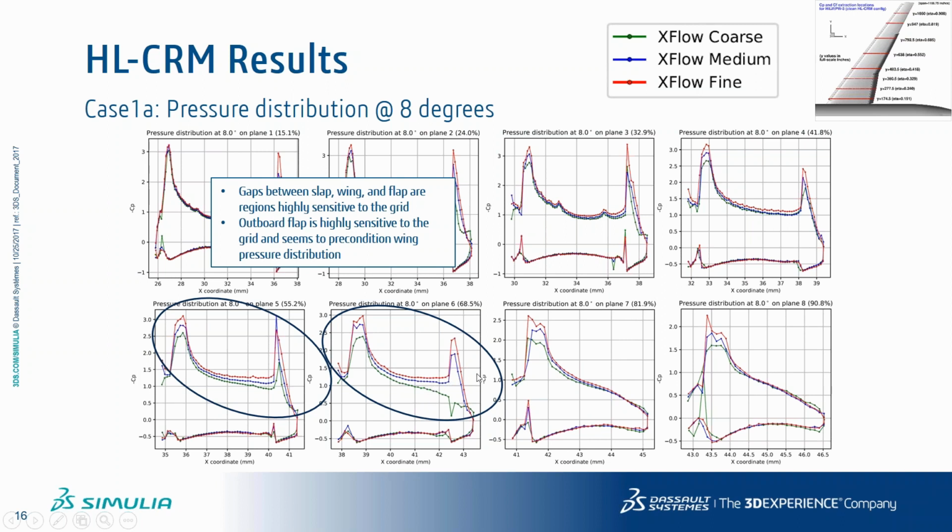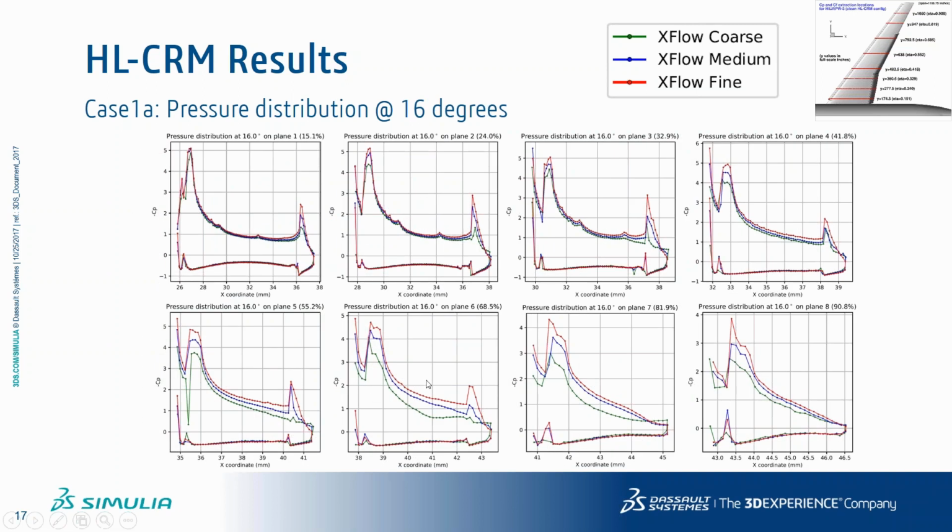Okay, otherwise, if you don't refine those gaps in this region sufficiently, you may just consider, as you can see on the green curve, it's almost a continuous blade element. It's as if it was a one element blade, a one element wing. Okay. So basically we need these peaks here to capture the correct flow mechanism. So that was for 8 degrees, but for 16 degrees it's pretty much the same thing.